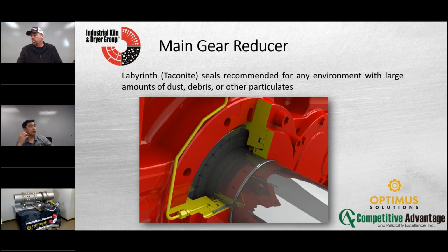Well, also, with your bearing or even with a reducer, most of the customer base that we work with, the material that they handle, like cement, is a pretty abrasive material. So it's like, hey, let's just throw some sandpaper in there and see what happens, right? So ultimately you've got aggregate or material in there that's foreign. These things rotate all the time, so now you're creating unnecessary grooves. You're creating wear and ultimately failure. So that's why it's good to do an oil analysis. It's good to figure out what all the components are, either for debris or for wear.